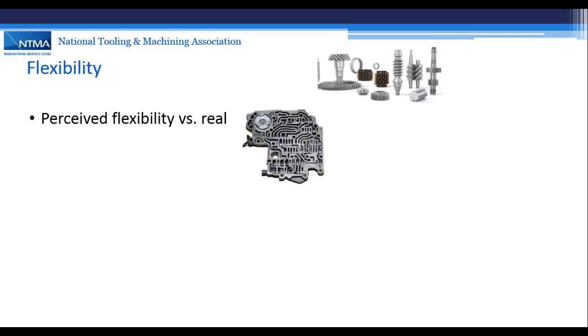But the main thing about the flexible systems is that when there's changeover, we can actually make those changes relative to work holding and programmability to make another part inspection. But that takes time also, and it takes maybe a skilled operator to make those changes. So even though this machine may be flexible from the capability standpoint, there are additional requirements to make that actually happen.